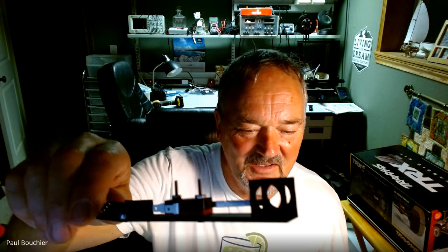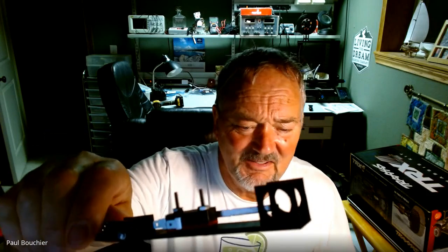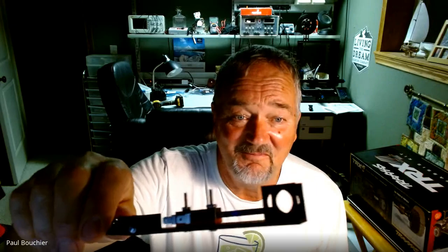Like you say, you can get away with some weird things, like you can have 2 posts with a bridge of about 2 centimeters, and you can actually bridge across it. It's just things that you couldn't even think about doing in other filaments. I was really surprised that it printed these fairly large 14 millimeter holes, about 9/16 of an inch, and didn't need support or anything for them. They just printed fine.